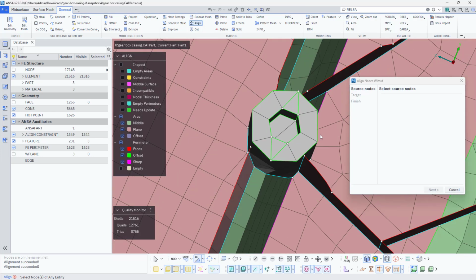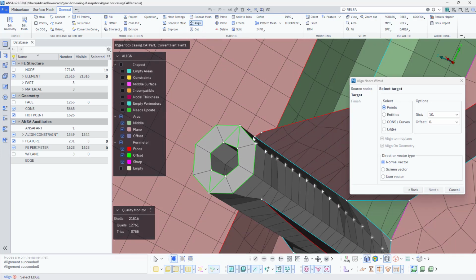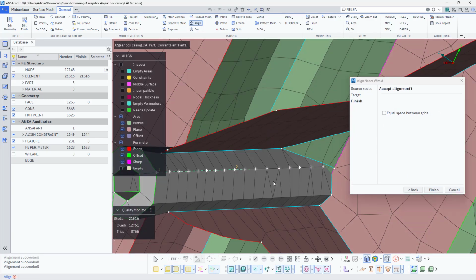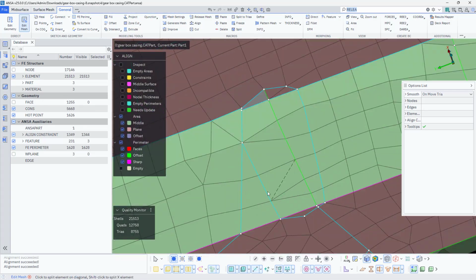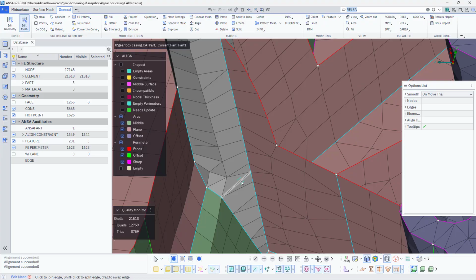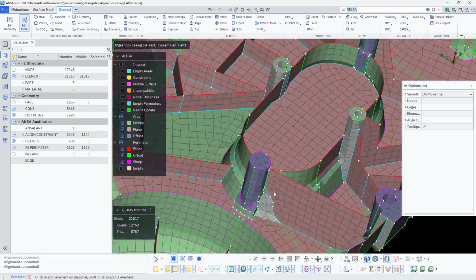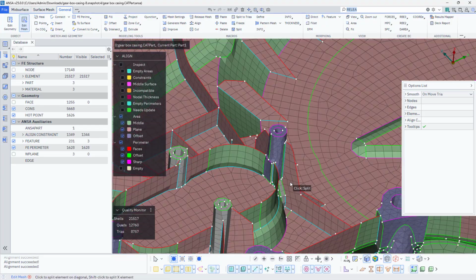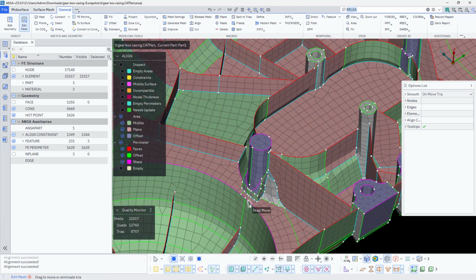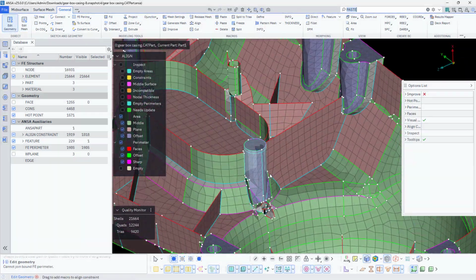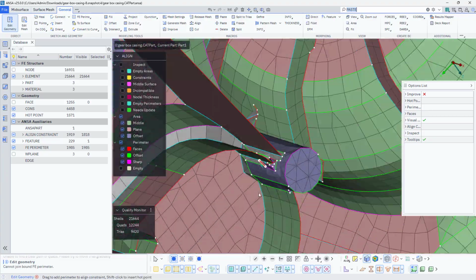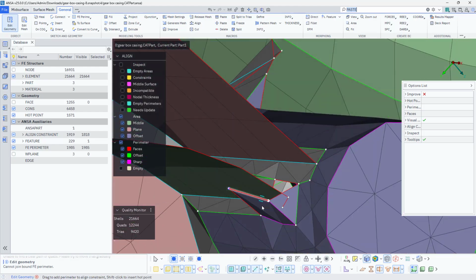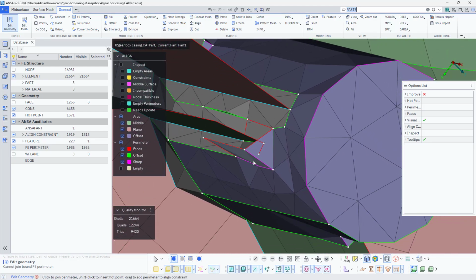Now after this, we're going to look at how exactly we can deal with the mounts which have been automatically created by using the automated option, and then fix them. You can just observe it. Let's see the automatically created mounts now. This mount is fine. You could see sometimes here it has created an issue. In these cases you need to manually edit them.